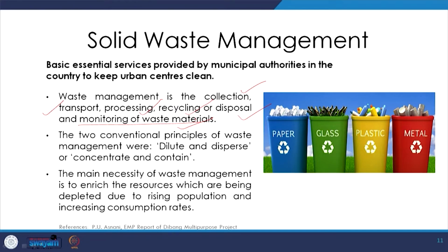So, there are two conventional principles of solid waste management. One is dilute and disperse and the other one is concentrate and contain. When we are talking about dilute and disperse, we are diluting the contamination. We are either improving the quality of it through dilution or through processing, and then we are dispersing it, so that it is not concentrated enough to create problems. In case we are not diluting it, we are further concentrating it and containing it in the form of sealed boxes.